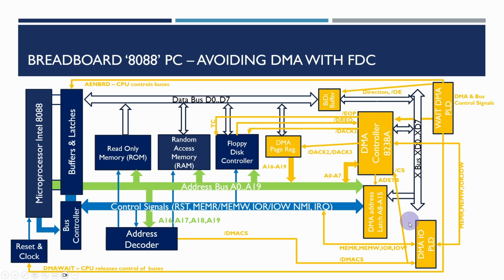Basically, all this orange stuff here we can avoid needing to have if we manage to get this programmed I/O working. So I'm pretty sure that if I can get this working, then it will simplify things substantially. And about the only other thing I can ever remember needing DMA, there might be some network adapters that could actually use DMA for reading data into memory, but I'm pretty sure programmed I/O could also be used.